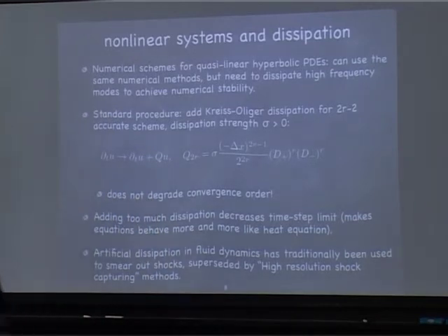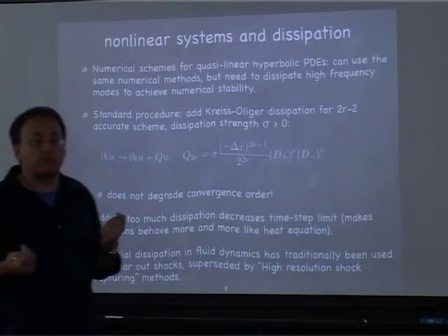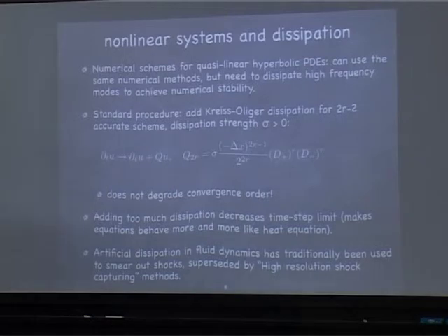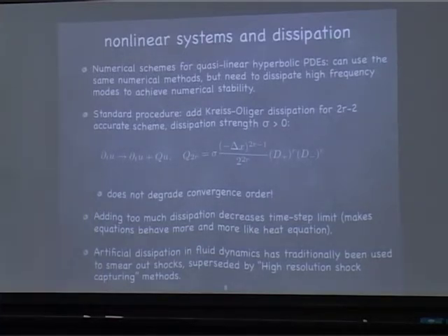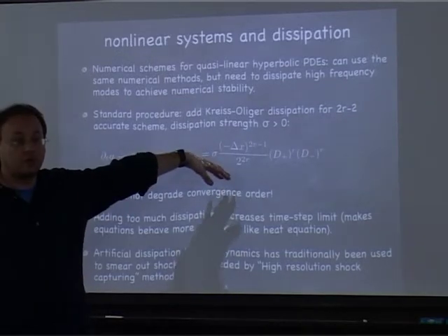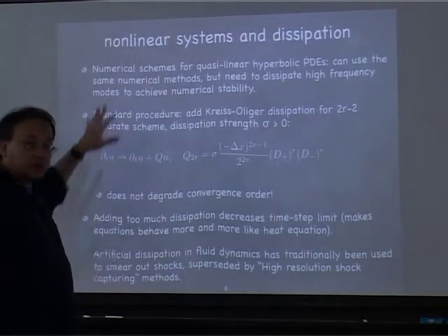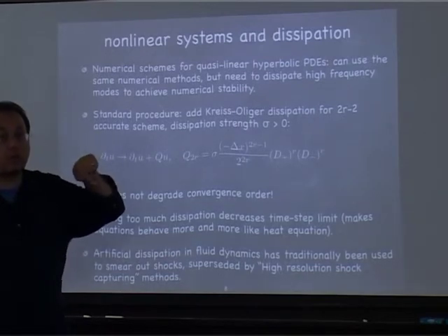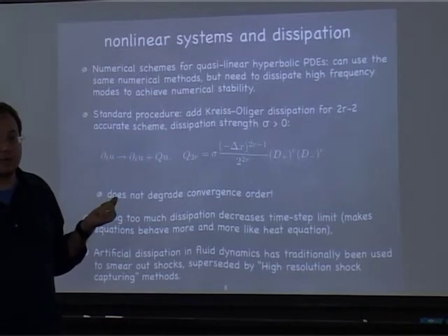Why? Because you can just prove a theorem that this has indeed the desired damping effect that we want to achieve. For r equals 1, this is kind of intuitive in the way that I explained, and you can just prove that in general this just works. This is irrespective of the real frequencies in your system. Well, if your solution is very poorly resolved, then this will have a strong damping effect, but just because you're poorly resolved. Okay, so you can only expect that everything together behaves nicely in the limit of delta x becoming small, which you have to find. What value of resolution you need? Well, you have to find by the convergence test.